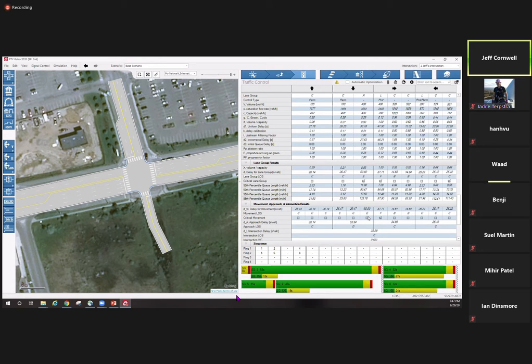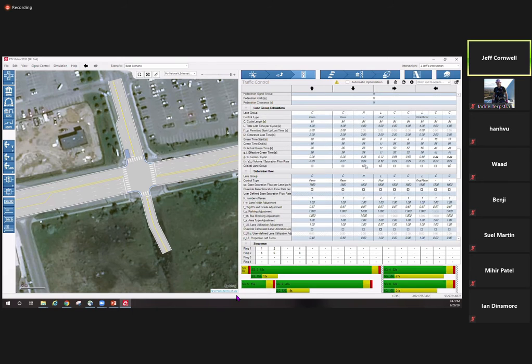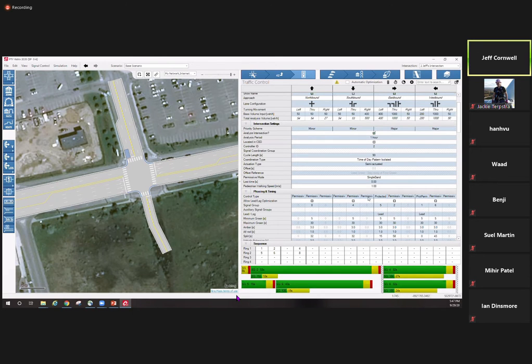now. So if you want to change that option and see what it does, currently I have level of service E, delay of about 60 seconds here. You could go up here, back to your phasing. And you could change this from being permissive to being an overlap. So now it's going to model that it's going to overlap while the left turn arrow is on for eastbound.